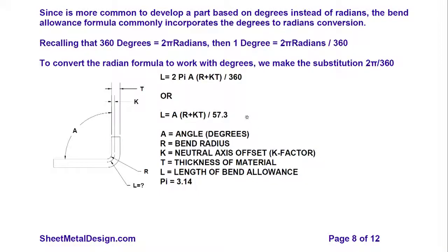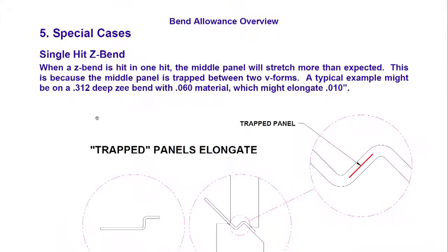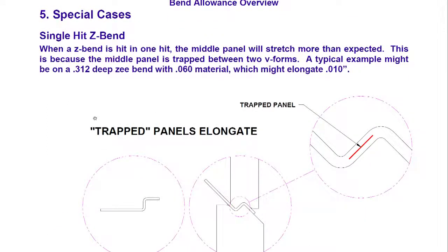So, I have a flat piece, I have internal plus a little bit of bending element. So, in our case, there is a 0.5 mm radius and all that, we come with 0.65 millimeters. So, we try to include that in various development calculations. But if you come here, there is a very elaborate thing saying for all other angles where A is in radians, elaborate calculations are given here.